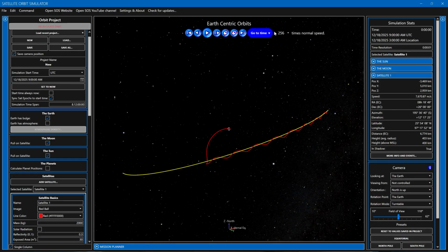Just remember that there are few windows in time where you can reach the moon from this parking orbit. Theoretically, there should be 2 for each lunar orbit around Earth, or 1 about every 14 days. And each of these windows will have its own width in minutes or hours. The width of this window will be a function of how close the inclination of the initial parking orbit is to the inclination of the moon's orbit.